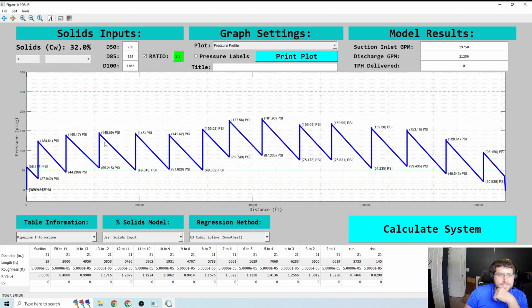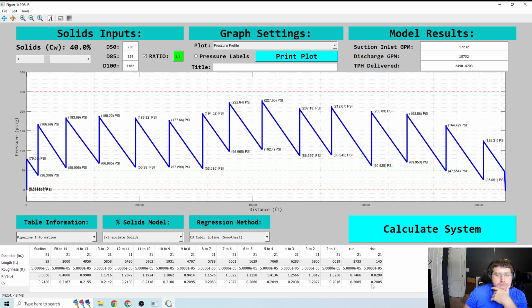I don't know what values you point to here, but let's take a look real quick. If I said, man, I got 0%, it looks good. I think it's close to like 40%. Yeah, I got 40%, it looks good. But getting there could be terrible. So that's kind of why I tried to code this, so that we can see some of the more transient behavior of the slurry pipeline as solids come in and solids leave, as well as, what if I have a really big density wave come through? Because that can exist in our process. So that was kind of the purpose of making this.